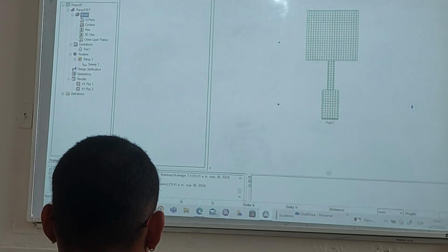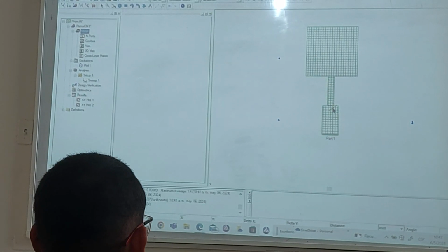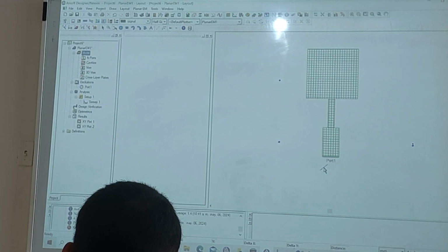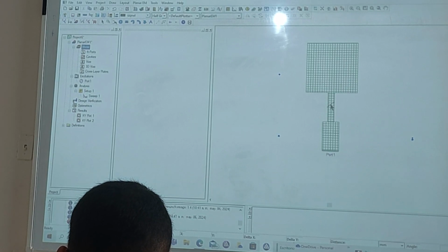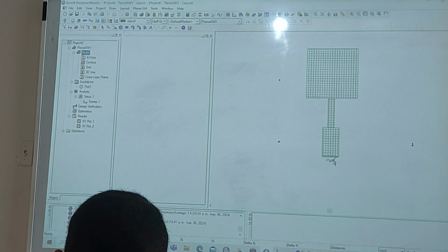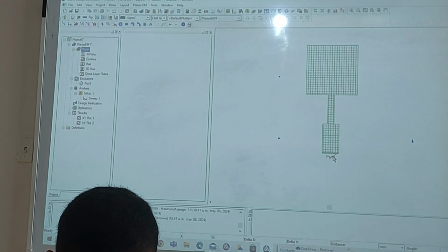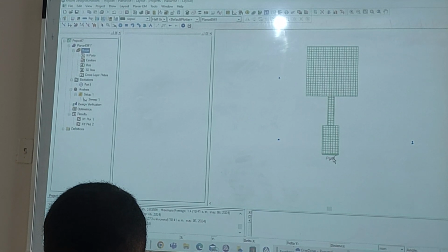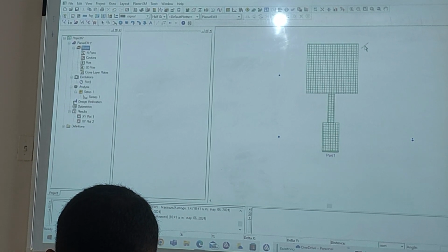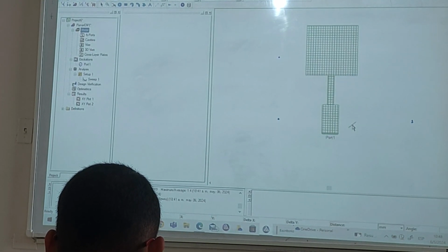The first one is antenna, where we find a low value real impedance, and after we make coupling for 50 ohms. And the other solution is to go to a higher real frequency and to make coupling in the same way. Then there are two possibilities. For implementation, this is the best one, because if you can see, the sizes are normal. I mean, you have here 23 millimeters, 3 millimeters, 7 millimeters. That is not bad to implement.